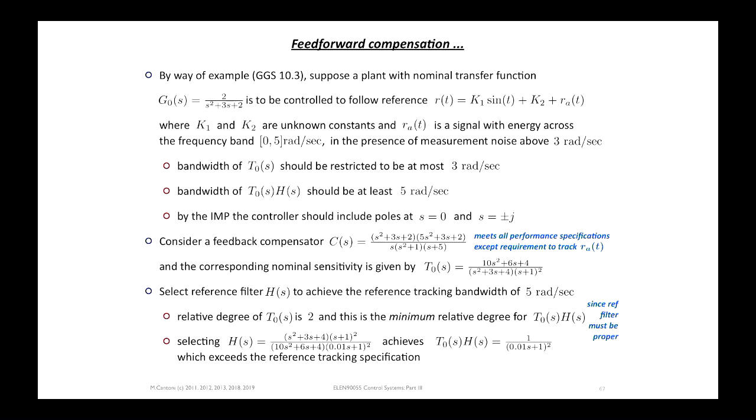All right, so here's a feedback controller. It has the pole at s equals 0. It has the 2 poles at plus or minus j. This guy cancels the stable plant poles. I know a lot of the examples do this, I'm just taking these examples from the Goodwin book. You don't always have to cancel the open loop poles, right? But by cancelling the plant poles, what you're left with is just the controller transfer function, and you just make that have the right shape to give you the lambda that you want, right? Because once you've cancelled the plant poles, then everything is in your control. So that's the rationale for doing that, but you don't always have to do that.